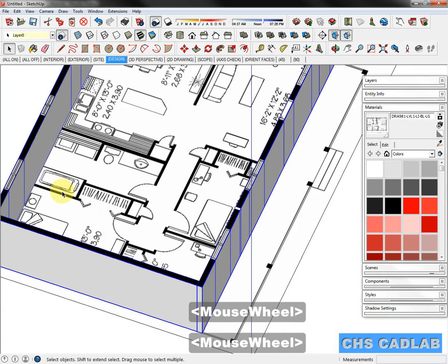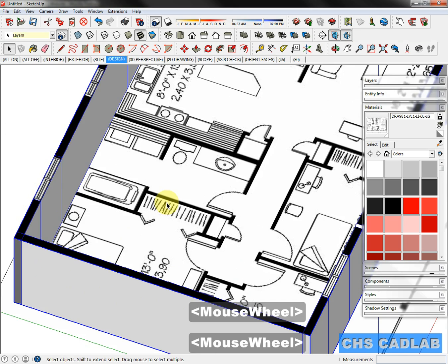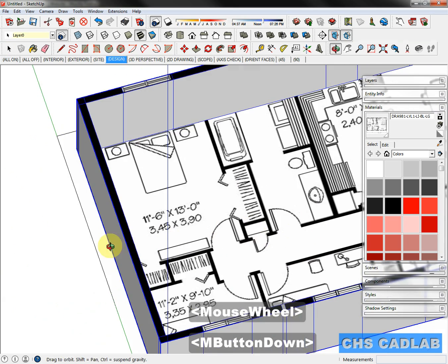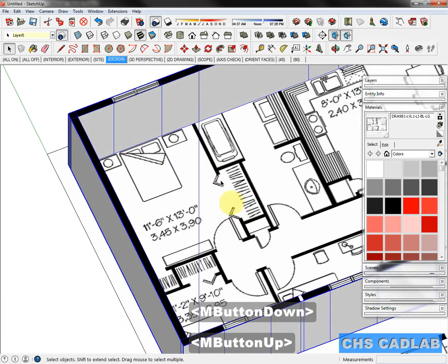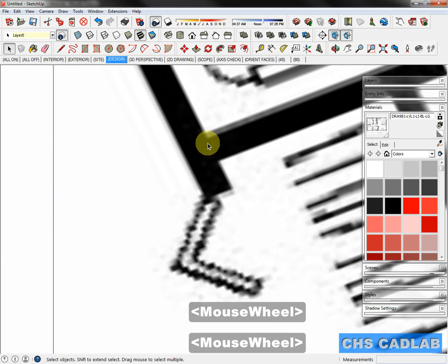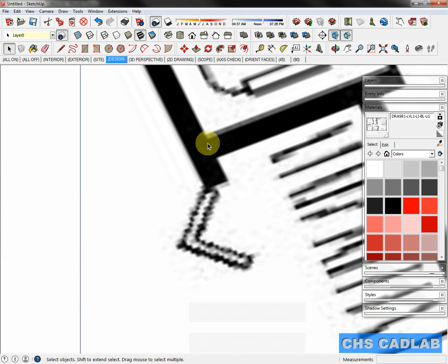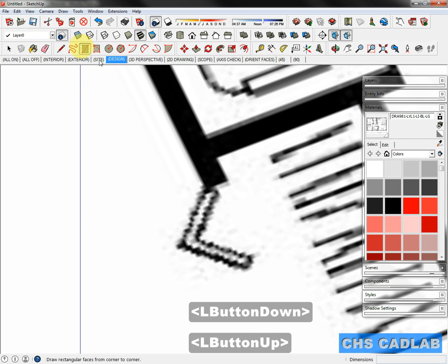Okay, so now interior walls. What is the typical width of an interior wall? 4 inches. So pick a spot on one of the interior walls, make a 4x4 square, just like we did, or a 4x4 rectangle.